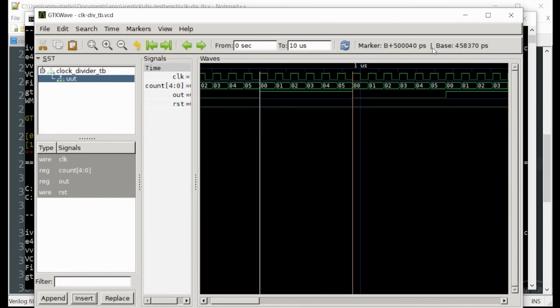So it's just pulsing a line whenever the unit under test does what's expected. It's a complete self-test, and you can have a full scripted suite of these self-tests to verify your complex design. But we won't get into that as things can get complicated quite quickly, but that is generally considered good hardware design when you unit test all of your different modules and different parts of your design.